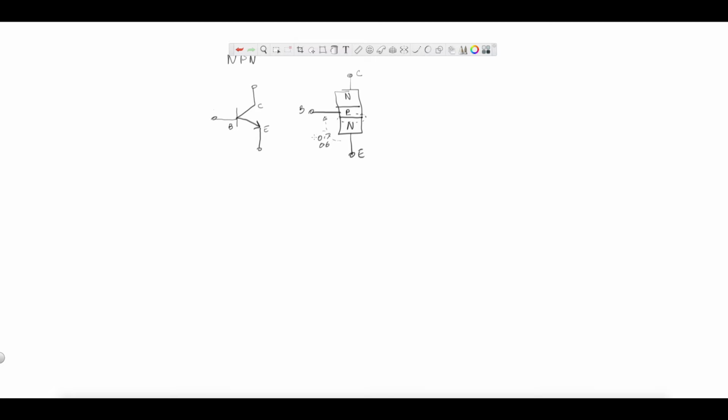But because of that, there is some resistance at this stage. So can we model this with that resistance in place? And the answer is absolutely. So here's our base here, and I'll model the collector side in a minute. So let's say we go this way, and let's call this one, the emitter, little RE prime. The prime notation we will see again later on. Right now, let's just call it a resistance. So we have some sort of an impedance between the base and the emitter due to the forward junction here.